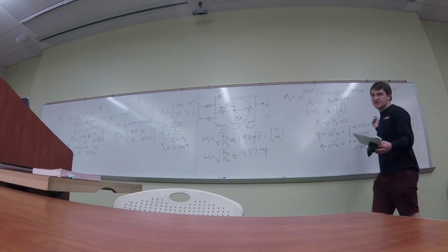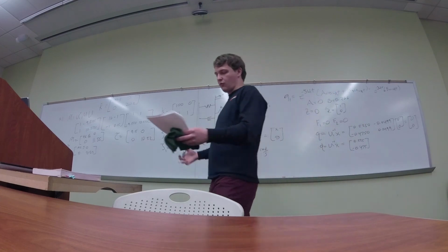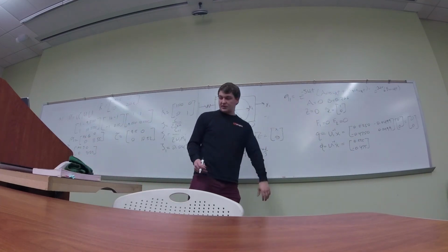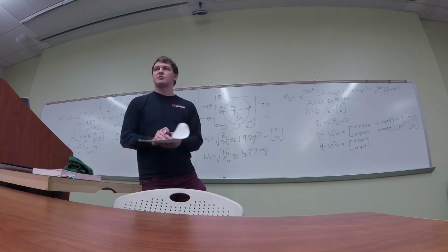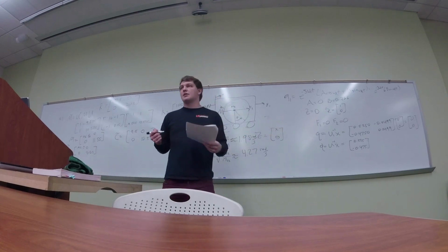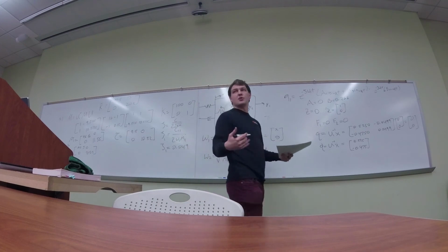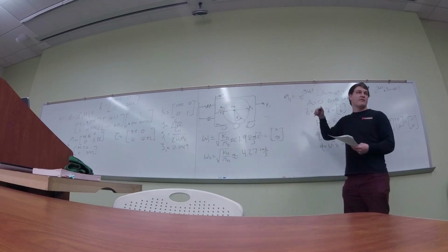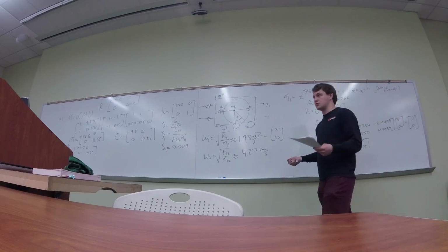So now you have this as just your equation of motion for q, and then x of t is going to be, and by the way, we're only looking at the response of the system, the contribution from the first mode. We're not looking at the contribution of the second mode. That's why we only have to solve for q1 instead of having two equations, q1 and q2.